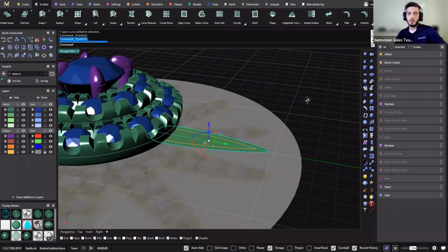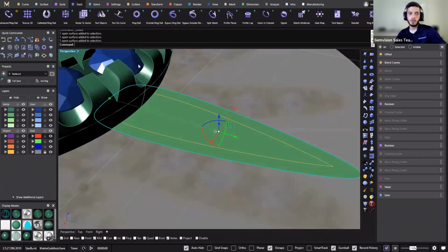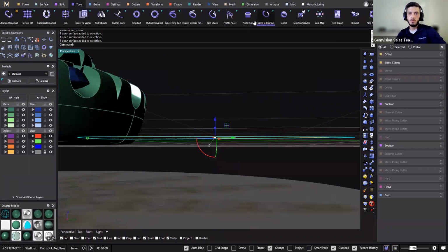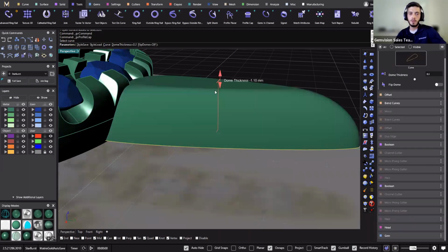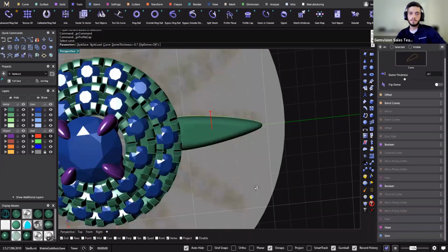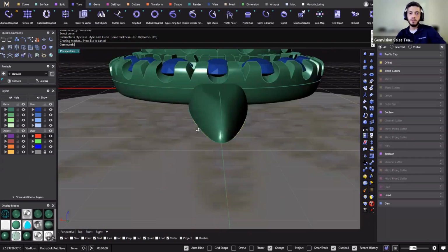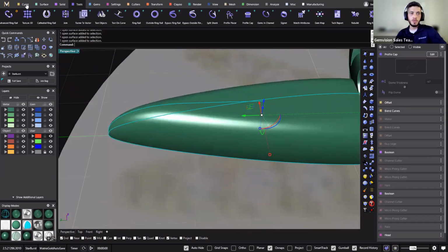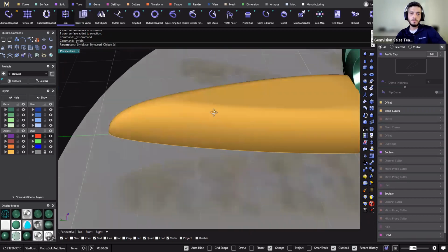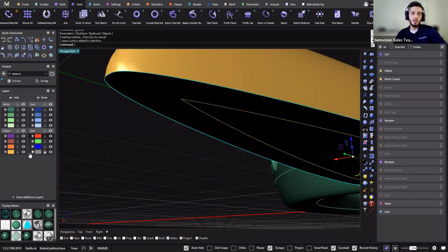All right, so back to this guy. So we can extrude surface. We can come here to tools. If you want it kind of pillowed, right? You can do profile cap. Something like this. Because I have made my surface down here, which is a Rhino command, I can now join them together. I will have a duplicate down here, but that's okay. I can just put them to blue and hide them.